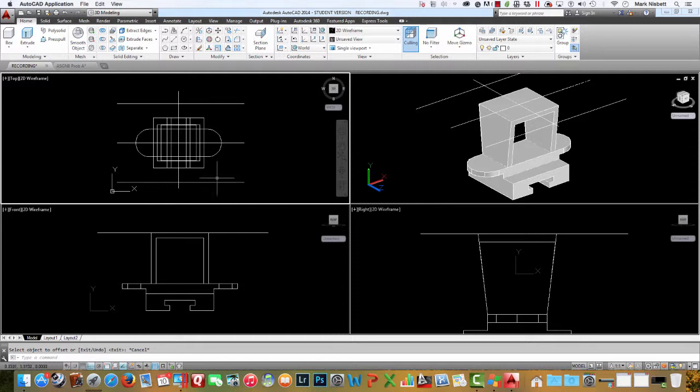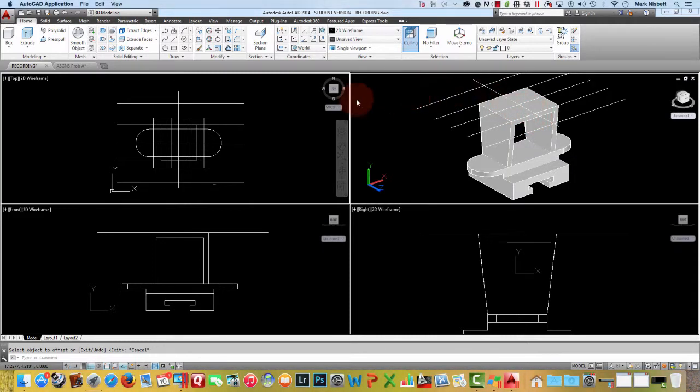Okay, and if we offset this in, because this is the quadrant, if we offset that in the radius of 1.7, that'll give us our center point. So we're going to go ahead and offset that 1.7. So we'll offset that in, offset this one in like so. You can see those occur right on the top edge of this, so that's actually good. And then we'll offset that 1.7, this line, to give us our width like this.